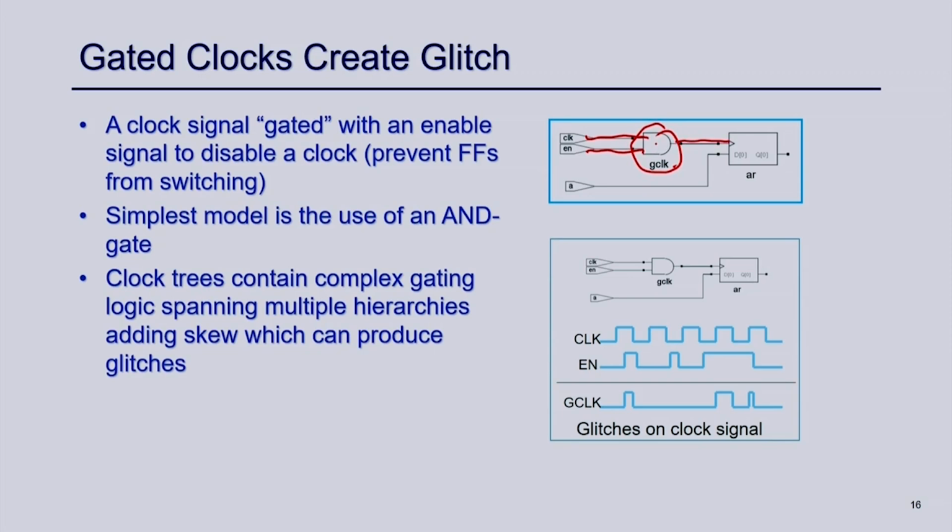Now, this enable may be glitchy, right, because I do not know, this enable may be glitchy and that glitch will propagate to this output of the clock and hence to the registers, right. So, how can we prevent that? The example is written here. This is my clock and this is my enable. You can see here these are the glitches, right. And this is the actual data 1. So, what is happening here, since the clock is 1 here and this part of the clock is 1.